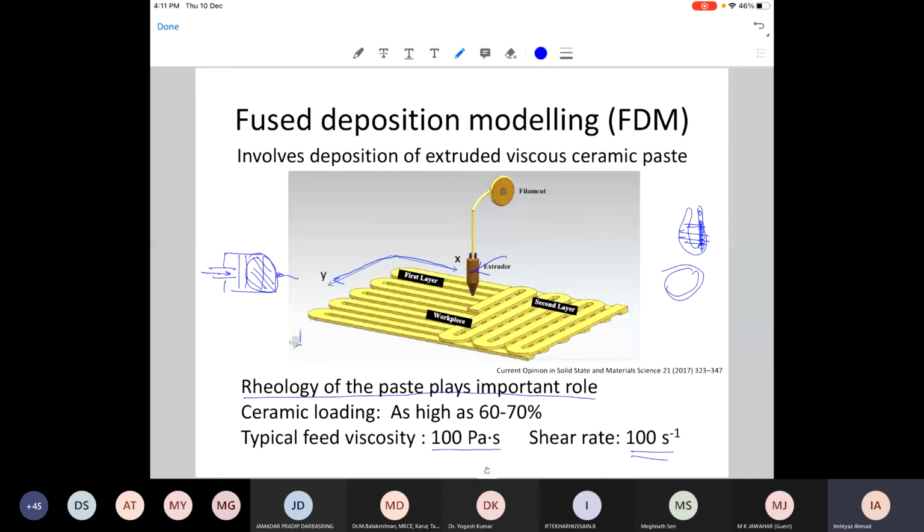But acrylates sometimes give very high viscosity. In order to take care of that, sometimes people add acetic acid or something which breaks some of these bonds and makes it slightly flowable. So by controlling these several components, you can get the numbers that are needed.